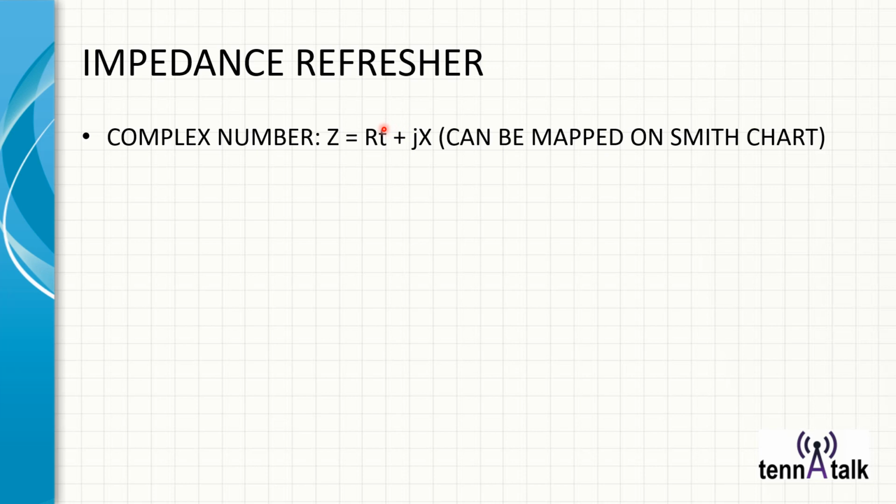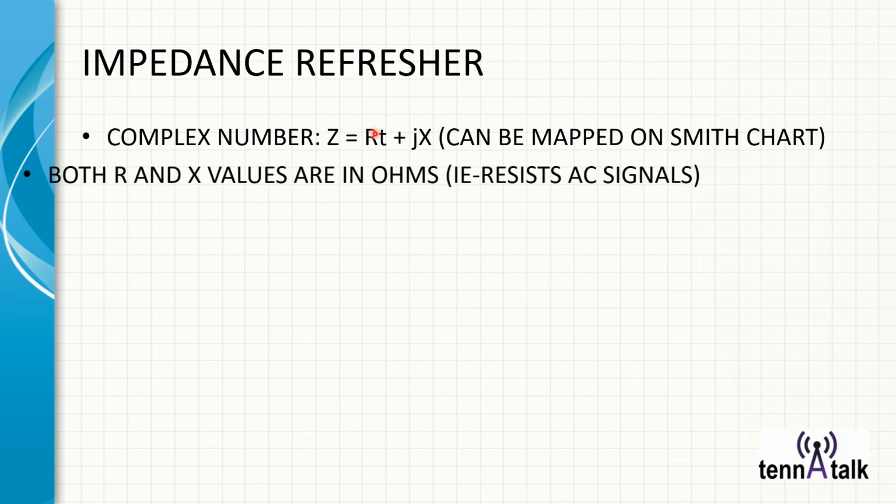Now, in podcast 3, I mentioned that this was the antenna radiation resistance, and that's not technically true. The ohmic resistance and radiation resistance are what this total is about, but most of the time the dominant value is the radiation resistance if you've got an efficient antenna and you don't have a lot of ohmic resistance in there.